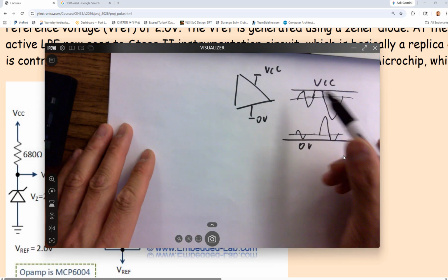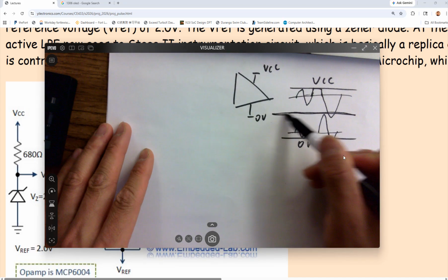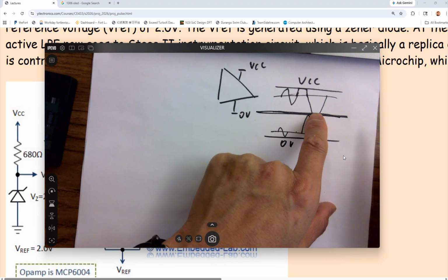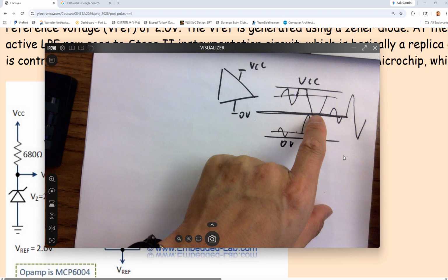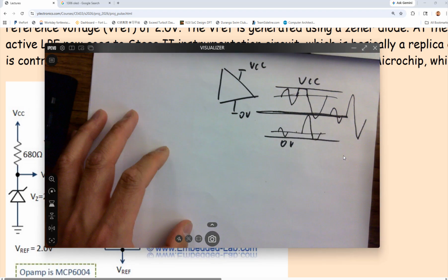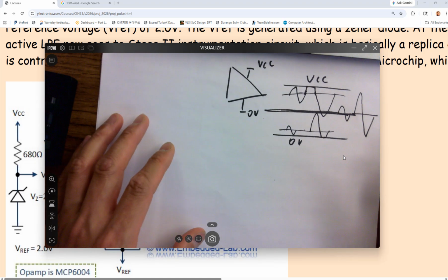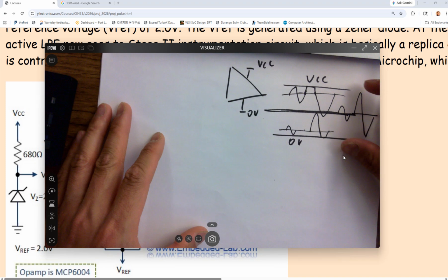So in that case, that's why the first step is to add a DC bias. Just lift your signal to the middle of the range. So you have a signal like this, you amplify it, and you have an equal swing towards both sides of the DC offset. You can leverage more space of the rail-to-rail voltage over here.